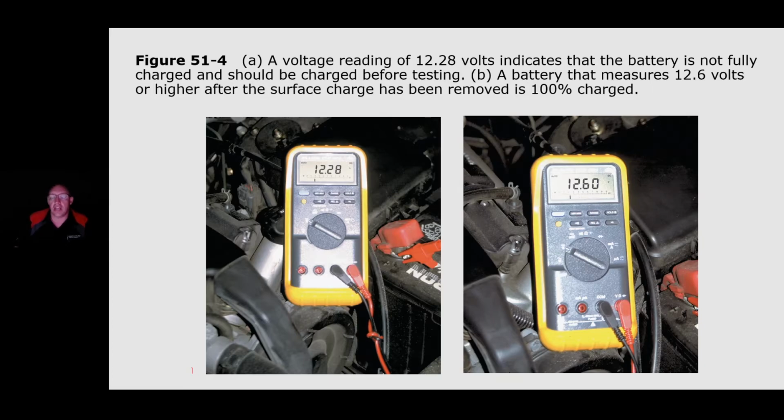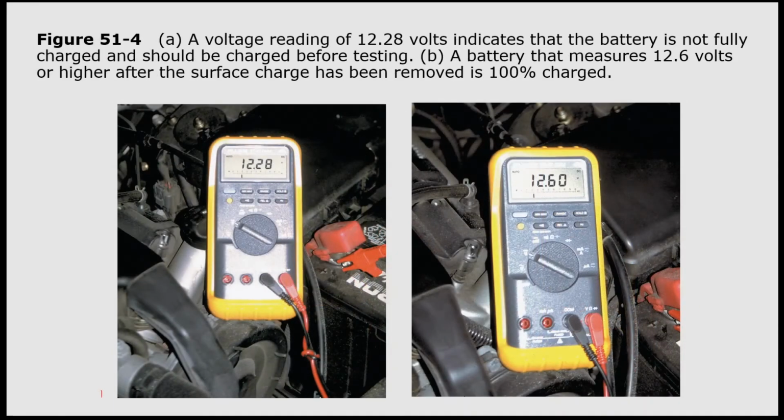Okay. Do not use the alternator on the vehicle as a charger. Emphasize that. Do not use the alternator on the vehicle as a charger, guys. Okay. Always use a battery charger as the charger.